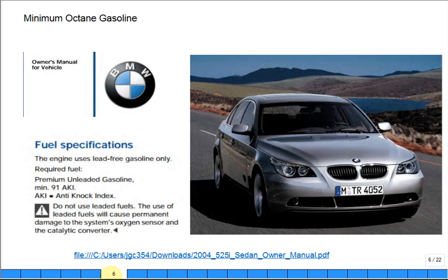Also, discussion about minimum octane number for your gasoline. Somebody in the AM section said, oh, the BMW, they require a minimum octane. So I looked up, I could get an owner's manual for this 525 sedan 2004. And the owner's manual says use lead-free gas only. Okay, that's great. You can't even buy leaded gasoline. But don't add the additive lead to boost octane.